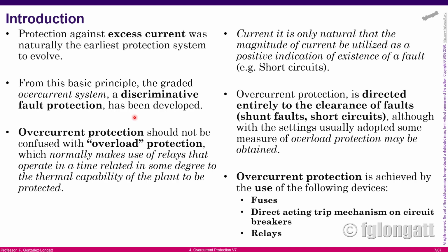However, something you must understand is that overcurrent protection should not be confused with overload protection. Overload protection is typically the one we use for low voltage systems, and it is related mainly with the thermal capability of the device, okay? What I am trying to say is that the overcurrent protection I will be discussing here is mainly the extremely high overcurrent related to classical short circuits, okay?